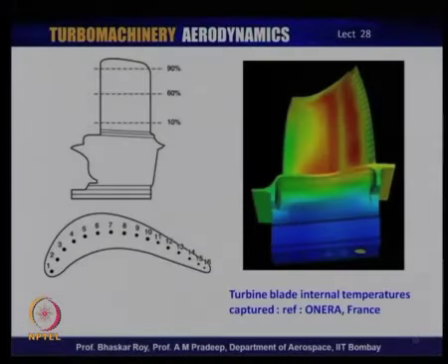So, that is where the cooling comes in. Let us take a look at the situation. If you have a typical turbine blade, and if you have this kind of, let us say, very simple cooling passages, so many of them, 1 to 16 of them, they have to run through the entire length of the turbine blade from root to the tip. So, typically the compressed air would be brought in from the compressor through the root system. You have the fir tree root fixing system here, it comes in here, and then it gets into these passages. Okay. You can have so many passages, or you can have 4 or 5 passages, as we have seen in the earlier slides, and they all then go through the entire length, cooling the blade at different places in a differential manner.